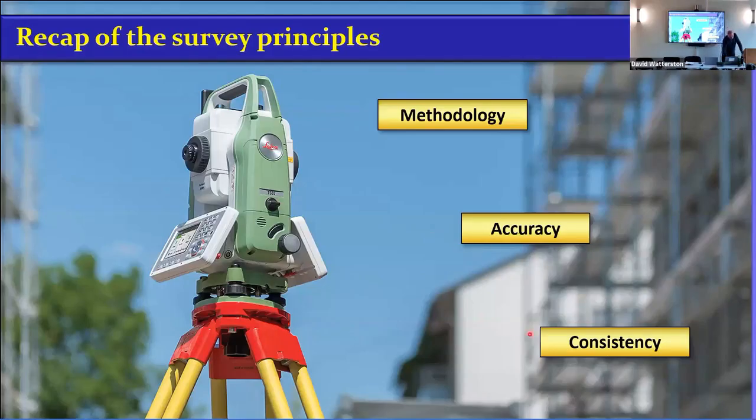And then consistency. Don't chop and change. If you're going to use meters, don't use feet and inches. If you're going to use millimeters on your drawing, which lots of architects use, a lot of people end up with just using centimeters. So it's plus or minus 5 mil. But when I've picked up things, I've struggled because I think it's millimeters. So where it says 61, I think 61 mil, but it's not, it's 61 centimeters.